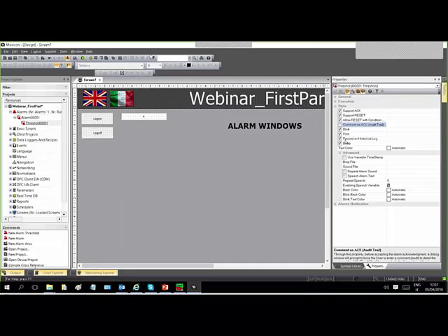Blink, print, go in the record in the database, beep, change the color of the alarm, change the background color of the line, the blinking color, associate the speech alarm text. It will be read using the speech engine of the system.